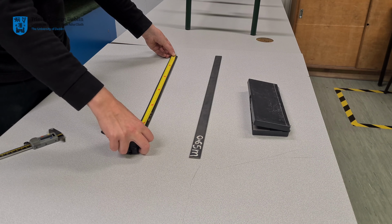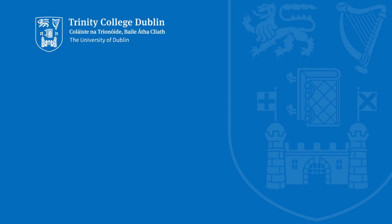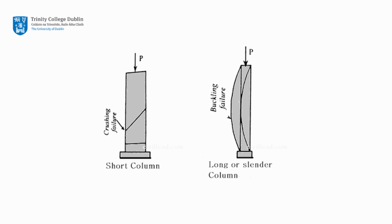Whether a structure will buckle or crush depends upon the slenderness ratio of the element. This is defined as the ratio of the effective length to the least radius of gyration. Since the radius of gyration depends upon the cross-section of the element, the slenderness ratio can be described as the relationship between effective length and minimum cross-section dimension. Members with a high slenderness ratio will buckle, whilst those with a low slenderness ratio will crush.